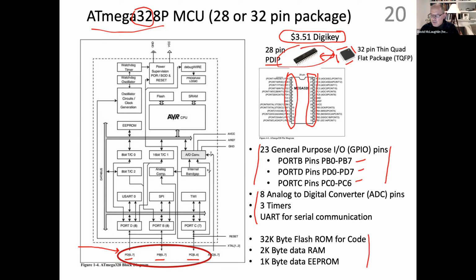Okay, question is, if you have a 328P, but it has the Arduino bootloader burned on it, will our code be able to run on it? We would end up wiping the bootloader off of it. One of the things we'll be getting to later on is dealing with the clock speed of one of these, dealing with whether or not the chip has a bootloader, and then dealing with the fuse bits, which are used to change certain things like the clock speed on it.